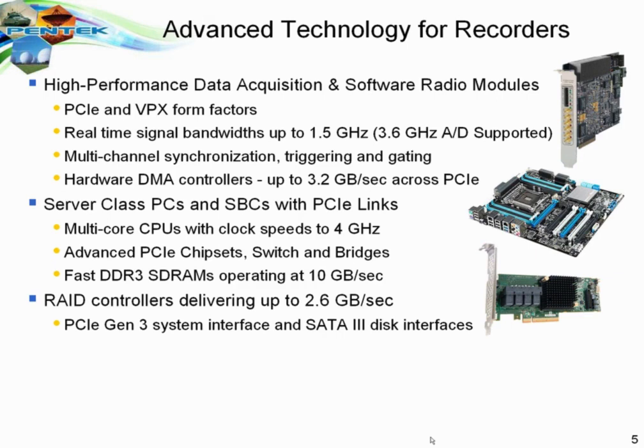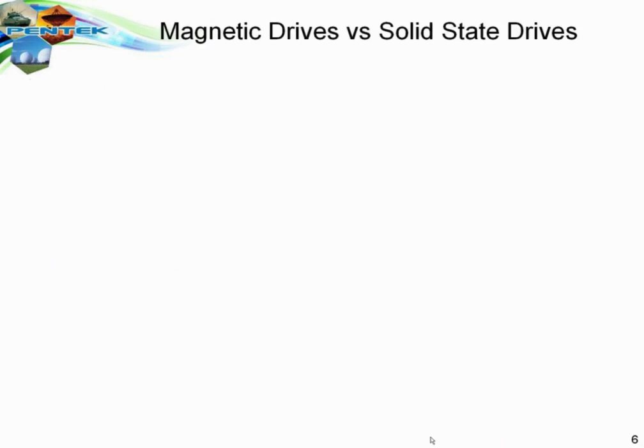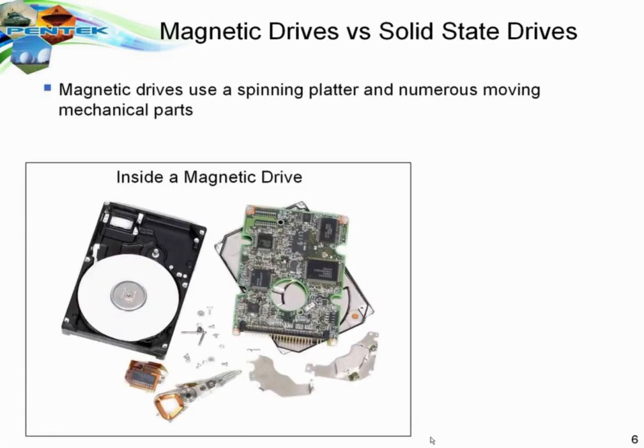They have a finite number, so in the processor that's part of a solid-state drive, you have what's called a wear leveling algorithm. What that wear leveling algorithm does is spread the writes around to even out the number of writes that any particular memory cell experiences. However, each of these algorithms varies from manufacturer to manufacturer and from SSD type to SSD type. So each type of SSD must be fully tested and characterized to make sure that you can use them for the sustained read-write performance that we need in the real-time recorders.